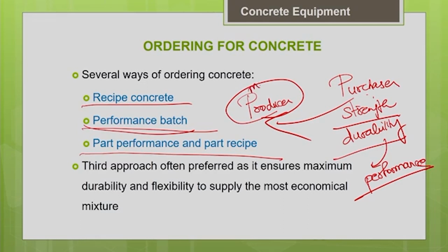The producer will do the mix proportioning. The producer will decide the mix proportioning. So he takes the responsibility of the strength and the durability. The producer takes the responsibility of strength and durability in the performance batch.